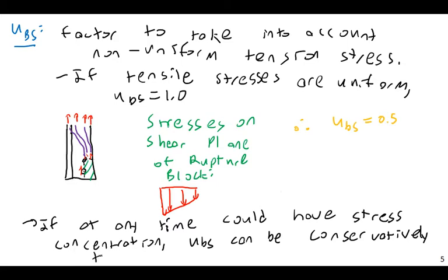Wouldn't every bolted connection have a stress concentration? Effectively, yes. That's what I was going to get at. Almost every bolted connection is going to have some form of stress concentration. In fact, pretty much the only way that I can think of that you wouldn't have some sort of stress concentration would be if you have a welded connection. Imagine you had a plate and a weld all the way completely along the edge of the plate. In that case, you couldn't have any stress concentration in that member because the connection takes up the entire length of the member.